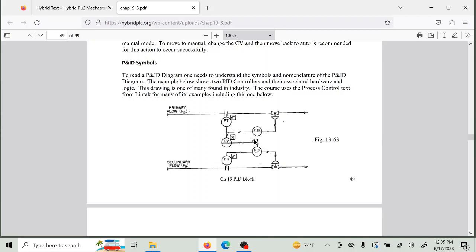You don't always see the word set, although they put it here in this case as a set point. This is the PV for this one, and this is its output. So this one has a flow, this one has a percentage of that flow. So whatever this flow is, this matches it to a percent. You say, is that guaranteed? Well, based on the tuning parameters, once this changes, this one has to follow it and change to catch up with it. So this is a flow ratio controller.